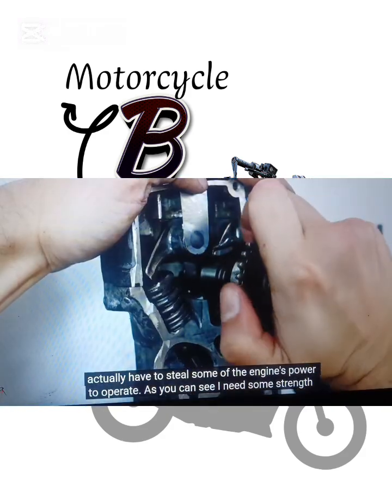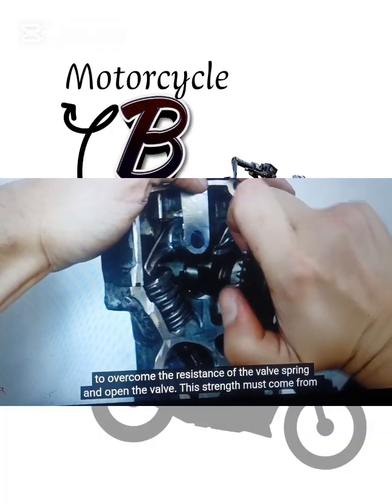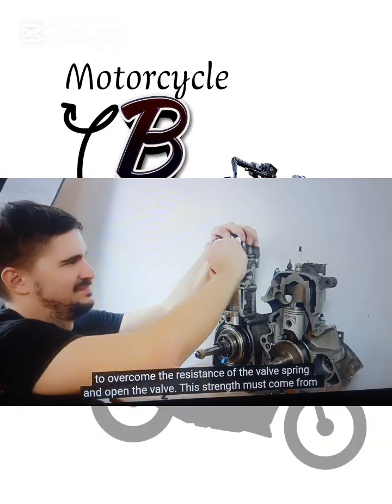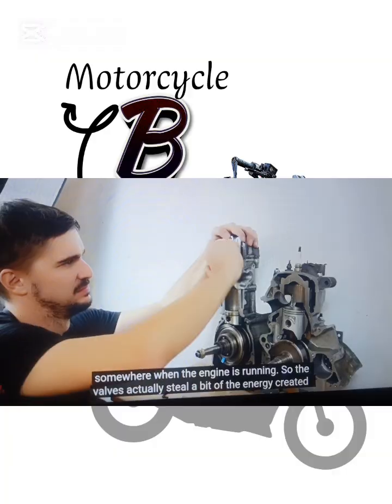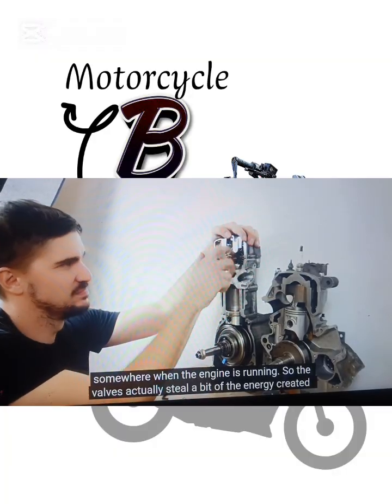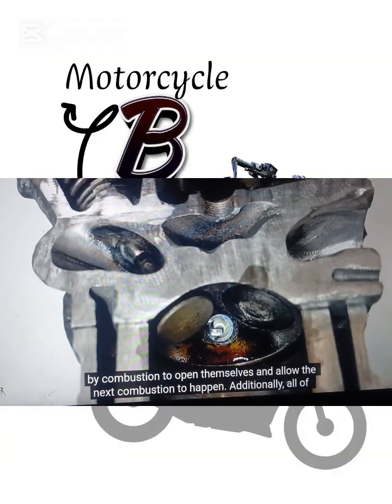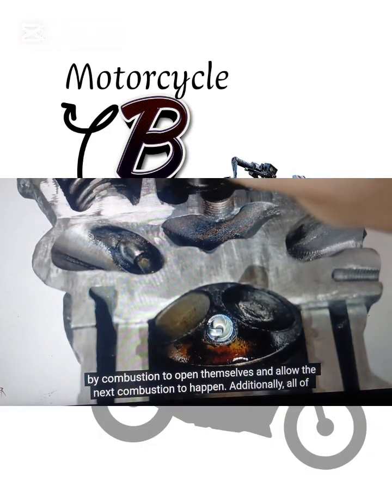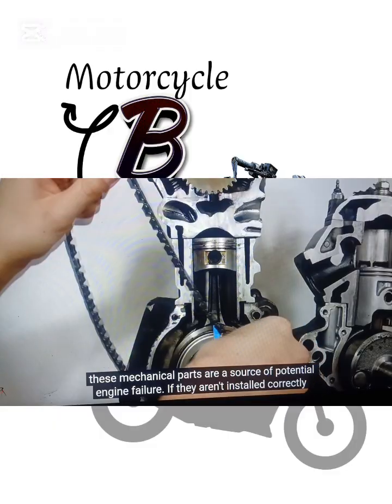As you can see, I need some strength to overcome the resistance of the valve spring and open the valve. This strength must come from somewhere when the engine is running, and so the valves actually steal a bit of the energy created by combustion to open themselves and allow the next combustion to happen. Additionally, all of these mechanical parts are a source of potential engine failure.